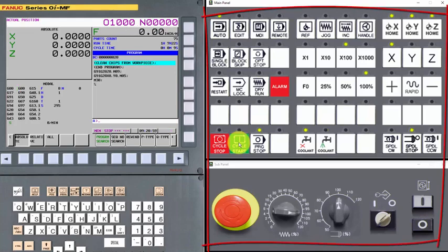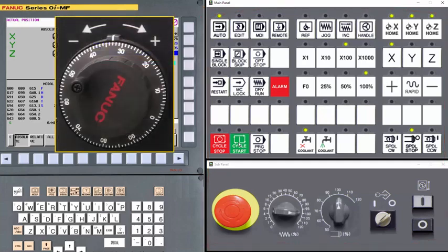For this tutorial, we will use this generic machine operators panel, an implementation of one of the generic machine operator panels available from FANUC, and it also includes most of the basic functions to run a program. One item it does not include is a handwheel or MPG, which is an abbreviation for manual pulse generator. The handwheel is an ideal way to manually move the axis, and it works pretty much like a handwheel on a traditional machine tool, except the connection to the axis is electronic fly-by-wire rather than mechanical. They are particularly useful for setup, allowing rapid, slow, and precise movement as required.